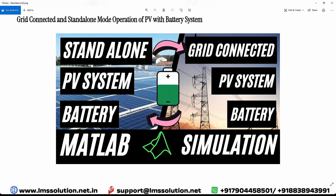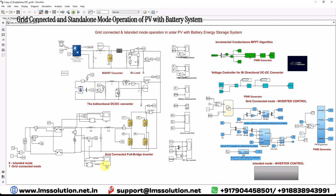For that, we already developed the models, both the standalone PV system with the battery and the grid connected PV system with the battery, in MATLAB simulation. Today I'm going to explain the operation of both conditions in MATLAB. For that, I'm going to open the simulation model. So this is a model created for standalone or islanded mode operation of solar PV with the battery system.